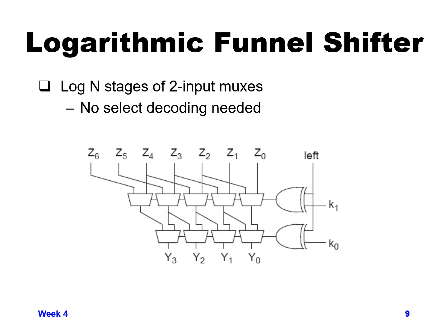On the previous slide, we went through an array funnel shifter, and while that might work pretty well for a 4-bit number that you're trying to shift, you can see how if we wound up going to, let's say, a 32 or 64-bit number, that gets pretty prohibitive. For example, a 32-bit number, which is not quite as large as modern microprocessors with 64 or 128 bits, would require 32 muxes that are each 32-to-1 muxes.